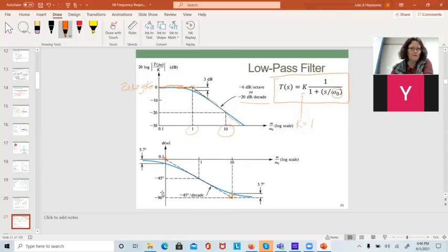Okay, low pass filter. Is the 5.7 supposed to be like a noise margin or a margin of error or something like that? 5.7. Oh no, the 5.7 degrees is how much error you have. Oh, okay. Yeah, because when you do the straight line approximation, you just do this. Right. And there's a 5.7 degree error at 1/10, and another 5.7 degree error there. So it is a margin.